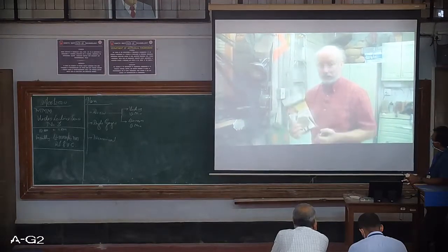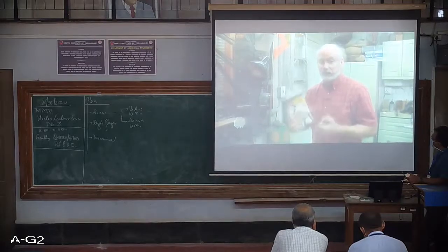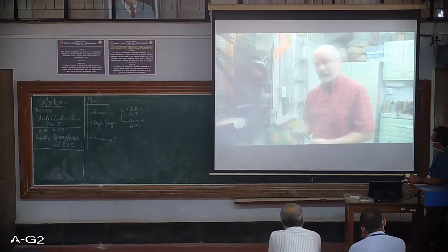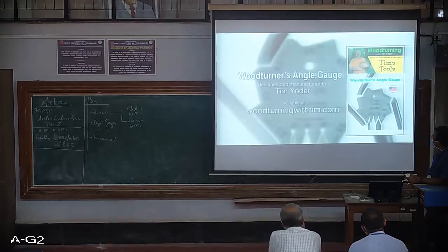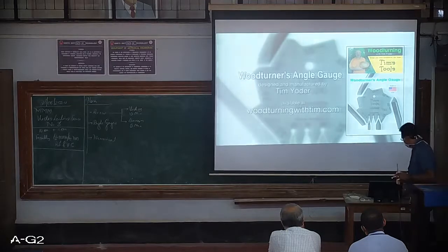But to me, if you have a dull tool, you have a dangerous tool. You have to have a sharp tool to turn well, but you also have to have a tool that you can repeat the grind on consistently, so when you approach the work, nothing's changing and it's always the same.